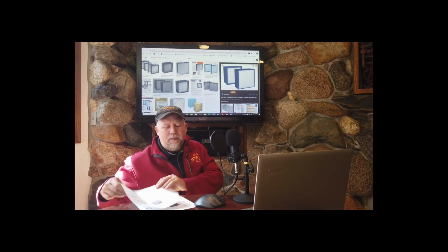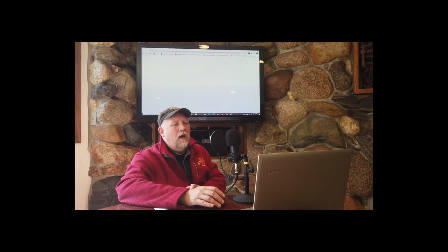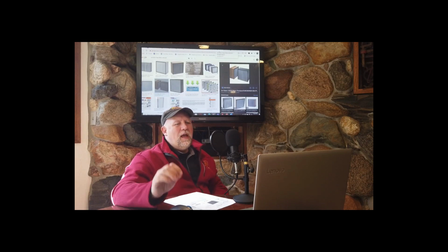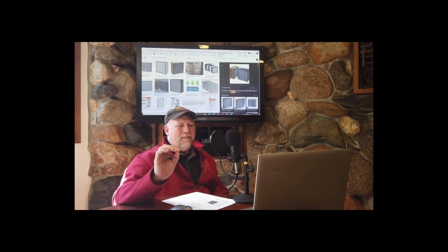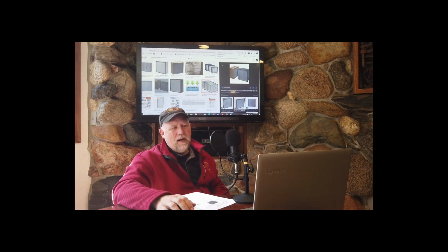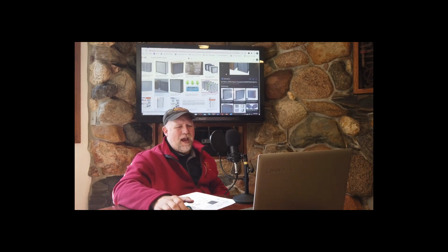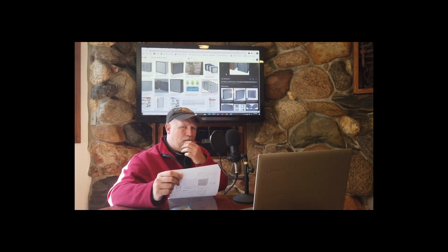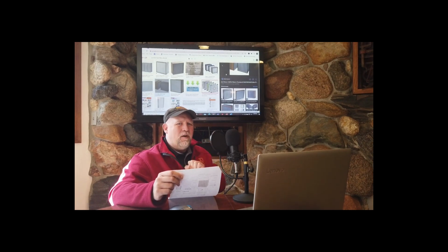All right, speaking of healthcare applications, let's go to the next one. High efficiency particulate air filter, HEPA filtration. A HEPA filter grabs everything. All right? And I know maybe not everything. If you look at the actual efficiency of these things, it's like 99.9999% efficient. Let's just go ahead and call that everything. The Ultracell HEPA filter is 99.97% efficient at a 0.3 micron size. We are getting down to the germ and bacteria level.